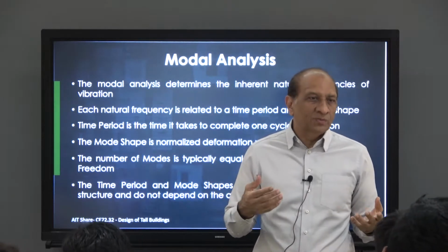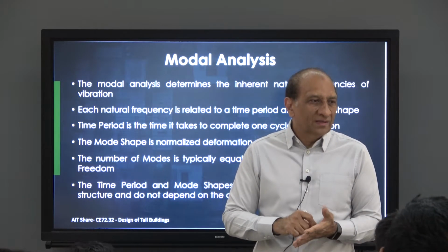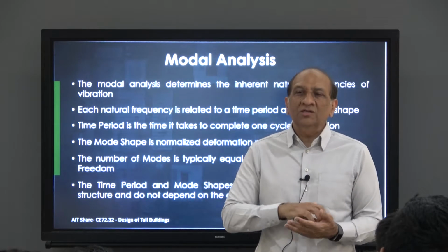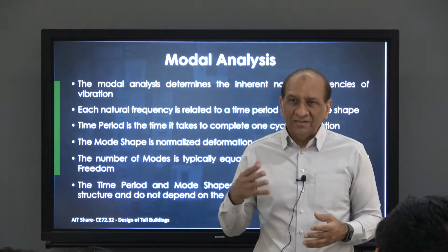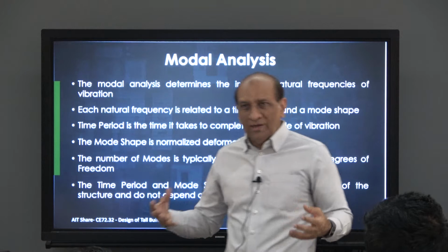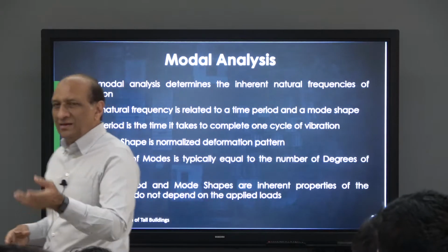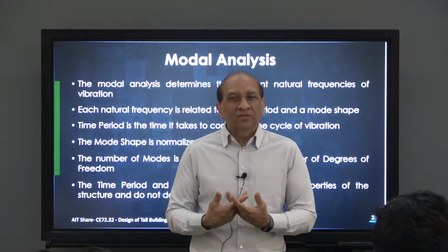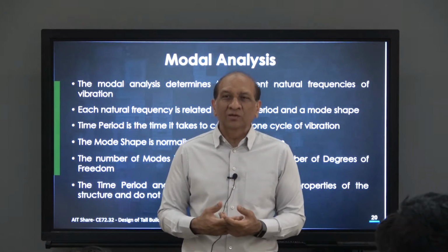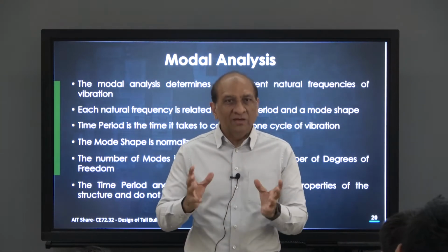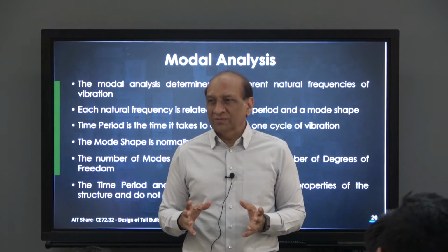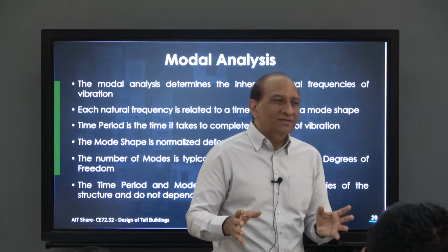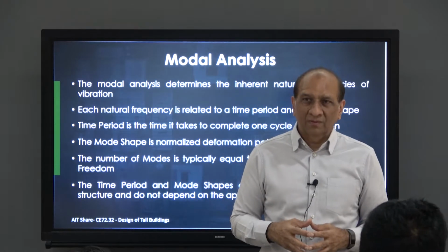So when you create an ETABS model, step number 1 is not dead load, not live load, not anything, just run a modal analysis and study the modes, isolate the problems. When we have a new project in our office, believe me, my personal input is 90% related to the balancing of the dynamic response, mode shapes and natural periods. That's what we work with, and once we get that right, the rest will be okay, right.